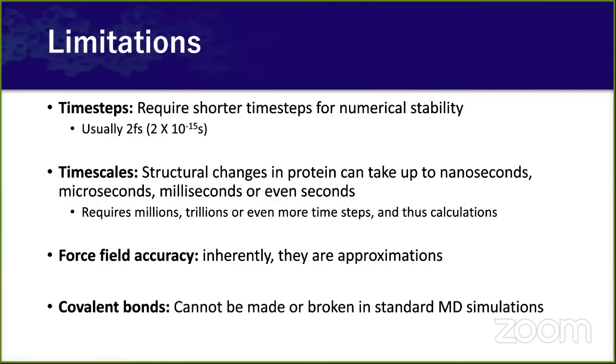As we discussed about time scale, these can depend on multiple parameters. But you also have to remember that the more you increase the time scale, the actual simulation time, I'm not talking about the computational time here, the more it will also increase your simulation calculations. When you're looking for a nanosecond scale simulation, you are already requiring millions of calculations to be done. When you go for microsecond or millisecond, you're talking about trillions and zillions of calculations, which will require very powerful computing machines to perform the simulation. So that is the limitation that you will have with respect to hardware and the time scale that you can have.